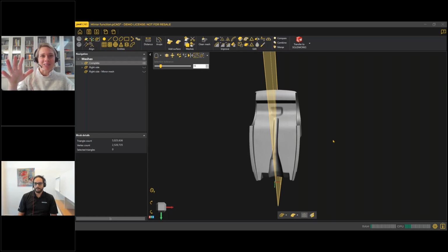Is that right, Marcio? Yeah. So in this software, we cannot import the CAD of the part, but in VX model or VX inspect, if it's inspection that you are interested in, I would go with the VX inspect, where you can compare a mesh to the CAD, and then you can do all the GD&T if you need. We have all GD&T functions to do the inspection of the part.